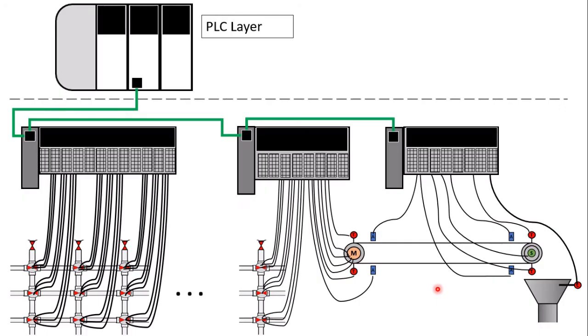So this is how our setup would look for our tank and conveyor system. The islands or connection points can be scaled based on the number of inputs and outputs that we need. You can also have spare I/O channels that you can keep for future use or use if one of the channels that you are using becomes faulty. As you can see in this example, you don't necessarily have to use all the terminals or channels that you have available. Of course, this is just an illustration.